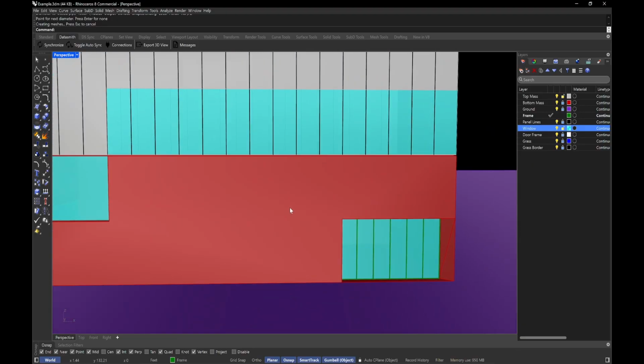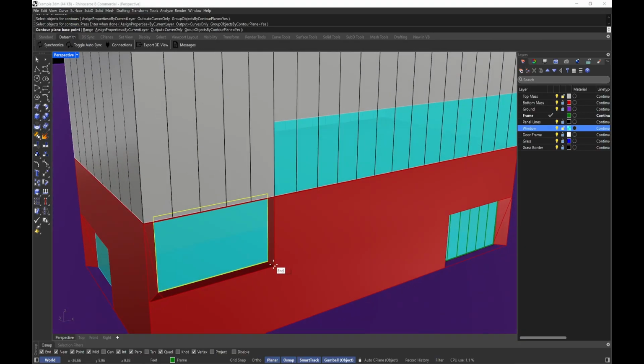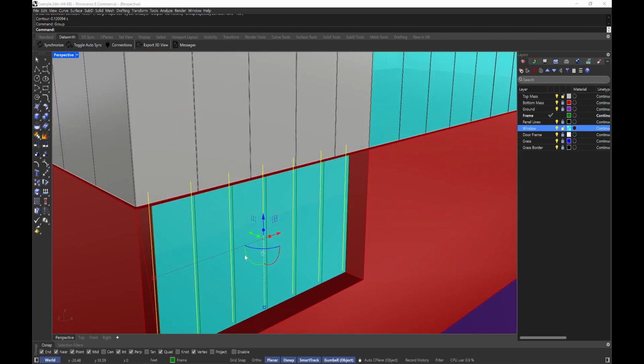The responsible way is if you want to make it like rectangular, what I would do is I would contour, right? Like that. And then I'll take, I'm going to group these. And then I would take these curves and extrude them out how deep the actual window frame is. So maybe like 4 inches or 2, your choice. So you get something like this, extruded inward though. Let me just take these real fast.